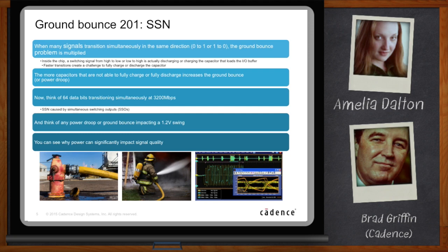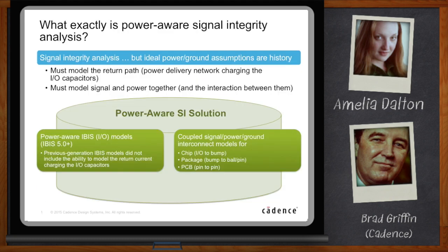So I think I have a reasonable grasp on the electrical principles, but what makes the analysis tools power-aware? Okay, very good question. It's something that we've been dealing with for a few years now. And kind of go back to this idea of signal integrity tools, just looking at the signal, but assuming that the power and ground was ideal. Well, okay, the job of the signal integrity engineer today doesn't change that much in the fact that he's still looking at the signals, but the tools can no longer assume ideal power and ground. Right. That's really the big change here, is that the power and ground assumptions are thrown out the window.